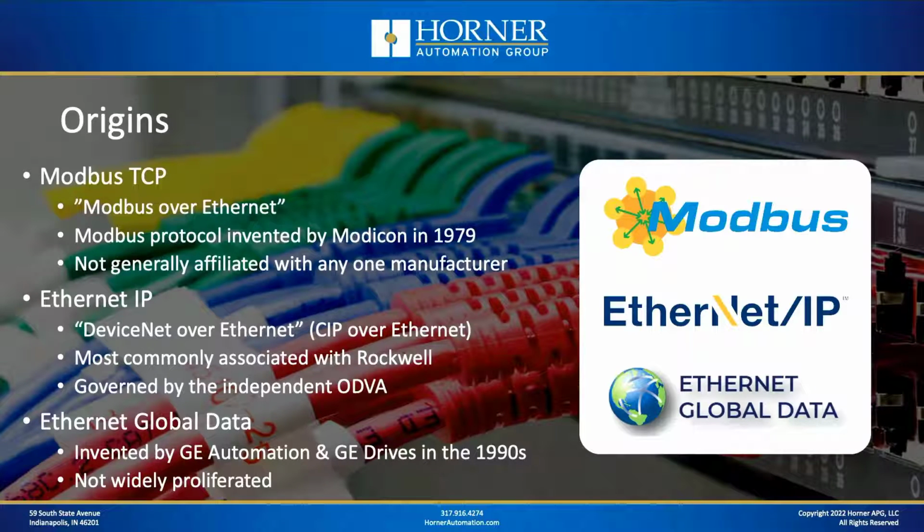So let's start with Modbus TCP. It is thought of as Modbus over Ethernet. Modbus protocol was developed in the late 70s by Modicon as a serial protocol, typically used in RS-422 or RS-485 or sometimes RS-232 type media.